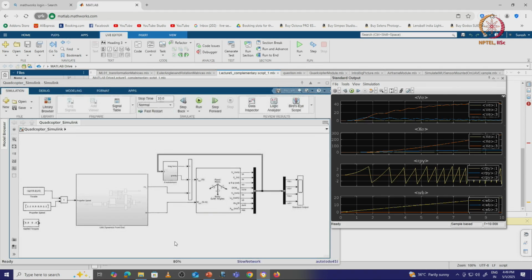That is very important. Remember, not all states are measurable. If I use an IMU, I get acceleration and I get my rate, but I may not get my attitude. I have to do estimation. We will talk about estimation. Once we have all this information, we look at the simulation again with sensors, scenario and estimation. That completes the understanding of modeling of the drone. Once we model, we look at control and navigation in a subsequent lecture. Thank you so much.